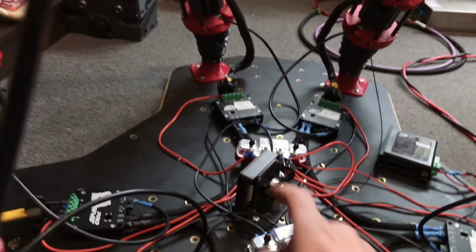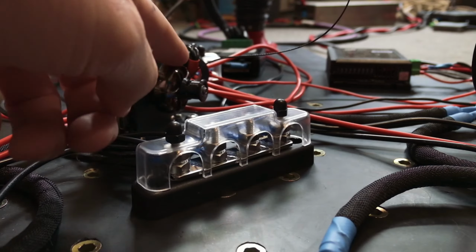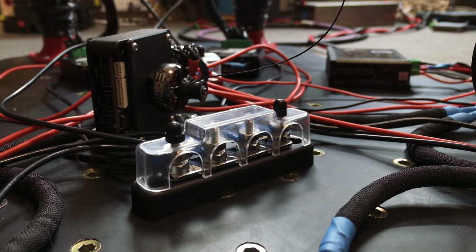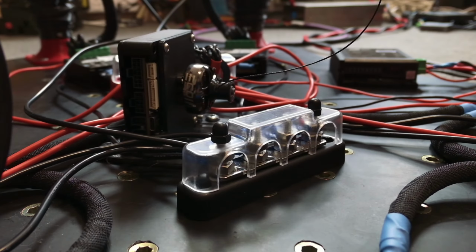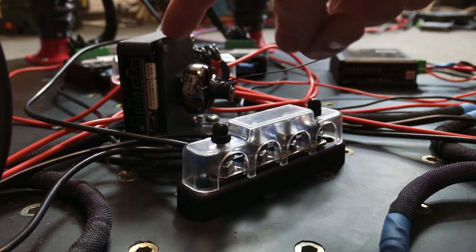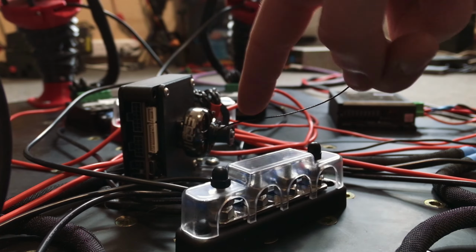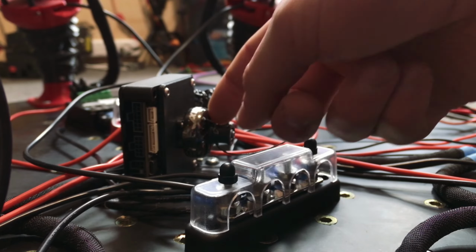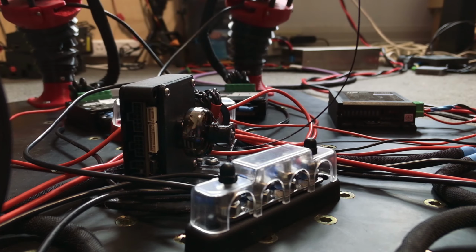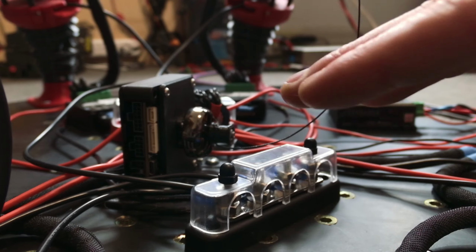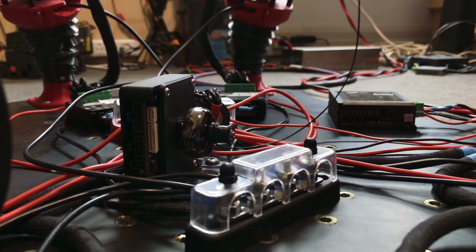The other thing that will be different is this hand motor, this is the setup that I was describing before. So we've got the motor with the drum. And actually, John, if you're still on now, I have seen your Zulip message and I need to reply to you. I've been a bit busy. But I want to send you the CAD files that I made for this because it was a little bit tricky to mount the motor in such a way that I could make use of the absolute encoder. I've had to be a bit sneaky, and honestly, it feels a bit dodgy because the magnet on the back of the motor wobbles a little bit when it's spinning really fast, but it seems to work. So I'll send you those files and hopefully we'll be able to recreate the same thing.